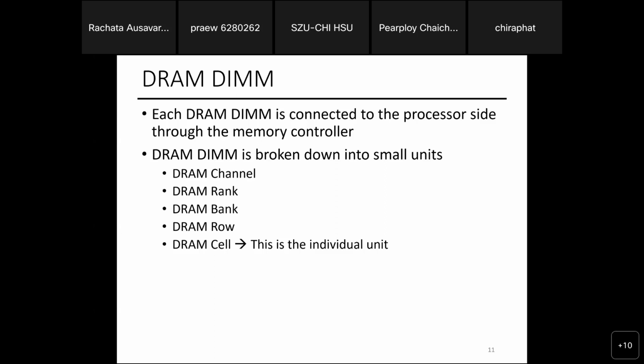The channels share the same clock. If we go back to an earlier question, I think 3 weeks ago, we talked about the clock. Why does it have a different clock region? Because the memory controller has the DRAM clock. That's the guy that controls the DRAM, which uses a different clock domain.